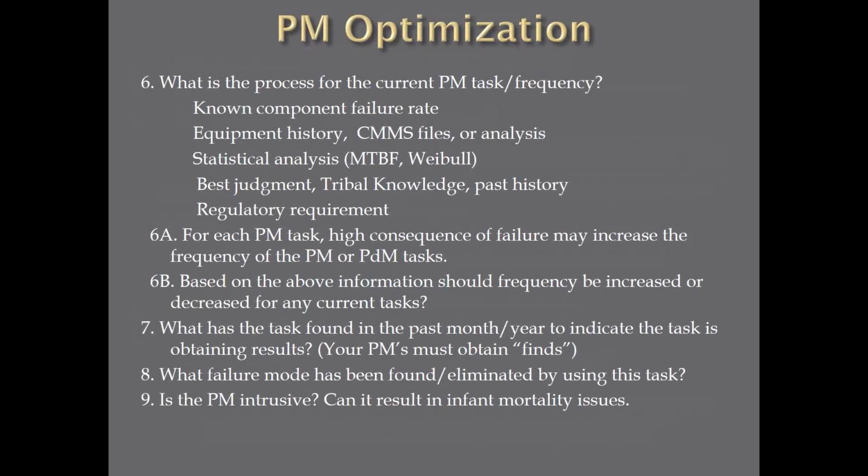We used to rebuild those gearboxes, and about 3 or 4 times over 15 years, we cut an O-ring putting it together, or we didn't get a gasket in right, and it failed a day or a week after we started. So a lot of times your PM tasks, the monthly and yearly things, can they result in infant mortality failures if we don't do the task correctly?